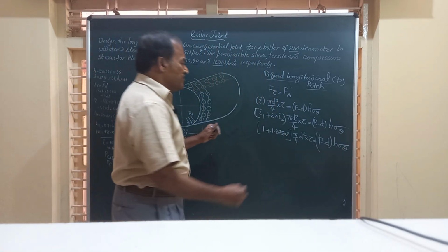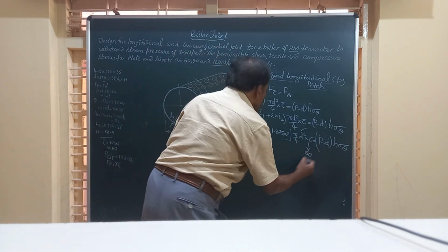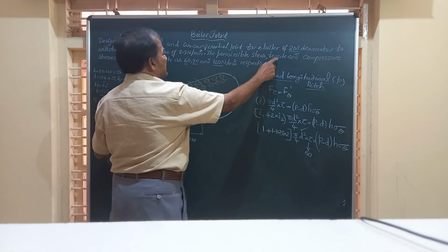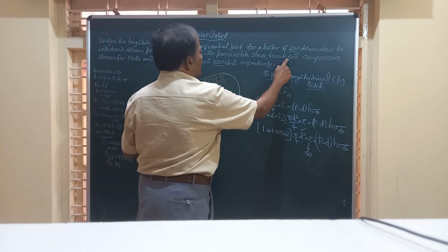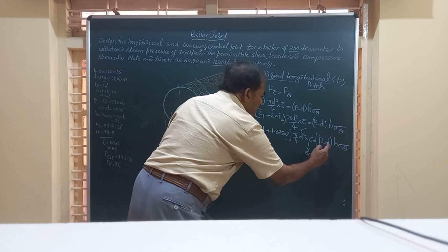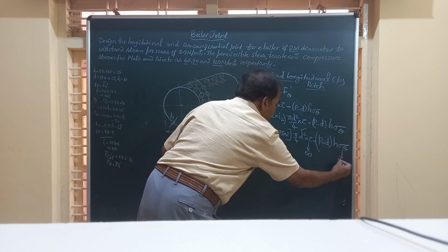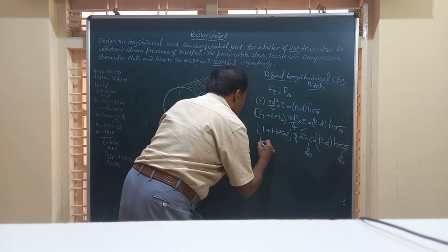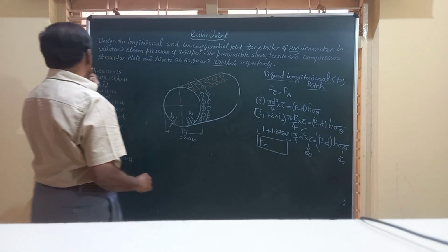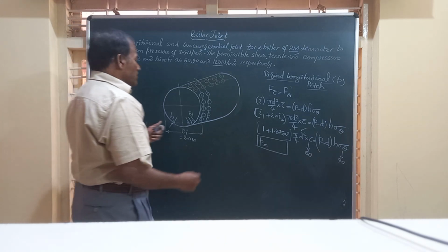Friends, here we know the value of D. The shear stress is given to be 60 MPa, 60 for shear, 90 for tensile, and for compression it is 120. So we have got these values. D we know, H is calculated, sigma theta is 90. So from this, you will be able to find out the longitudinal pitch for this joint. This works out to 147.082.